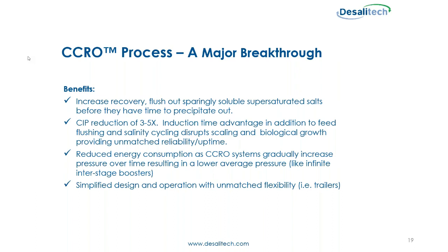So the other benefit is CIP reduction. We've seen a reduction of 3 to 5x. We have that induction time advantage that I just mentioned, in addition to the feed flushing and salinity cycling, which disrupts scaling and biological growth, providing unmatched reliability and uptime.